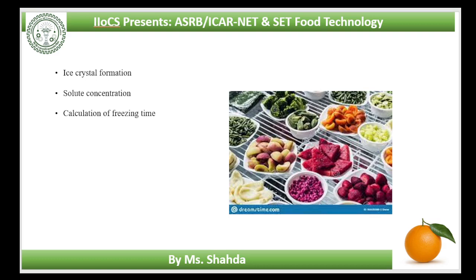The freezing point of a food may be described as the temperature at which a minute crystal of ice exists in equilibrium with the surrounding water. An increase in solute concentration during freezing causes change in pH, viscosity, surface tension, and redox potential of the unfrozen liquor. As the temperature falls, individual solutes reach saturation point and crystallize out. The temperature at which a crystal of an individual solute exists in equilibrium with unfrozen liquor and the ice is its eutectic temperature. Maximum ice crystal formation is not possible until this temperature is reached.